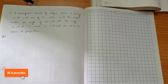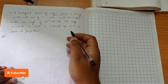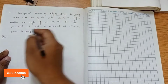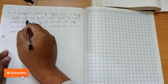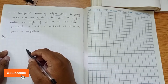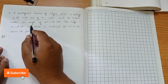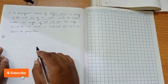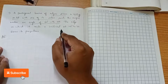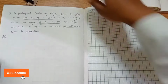So now we look at the question. A pentagonal lamina of edges 25 mm, so we have to construct a pentagonal lamina of dimension 25, and it is resting on HP with one of its sides. That means we have to construct a pentagon with respect to the edge on the left hand side. Now the inclination is such that the surface makes an angle of 60 degrees with HP. This is the inclination to the HP. Now the same edge on which it rests is inclined at 45 degrees to VP. So now we have to construct the first position.